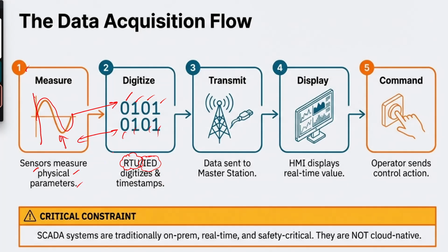And also the important part when we digitalize this data is we are putting the timestamp. Correct. This is critical, because the measurement is a continuous process, correct? At a regular interval of time, it could be 1 minute or 5 minutes, these signals will be coming to the device.